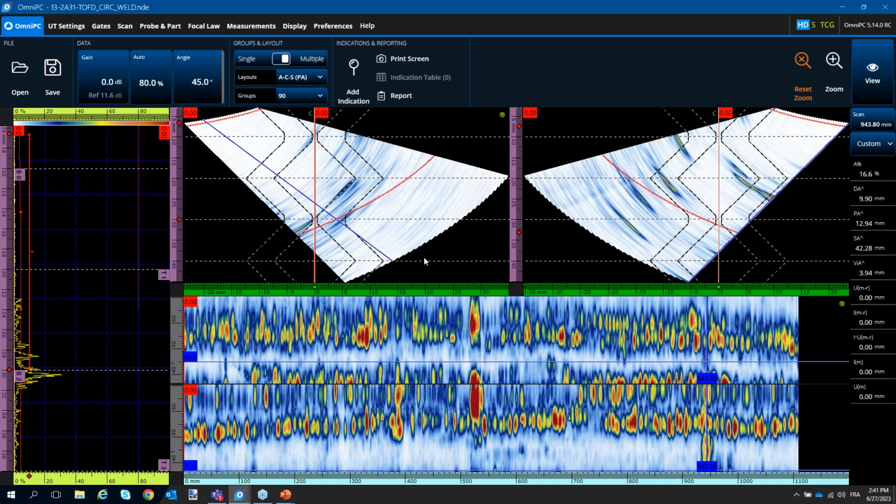So I can tell there are some indications. There are some stronger indications in there, but I want to try using the merge B-scan and compare what this will look like once I have optimized each view. Now this is a 1100 millimeters, 1 meter scan, just enough for displaying all scan slices in one stream.